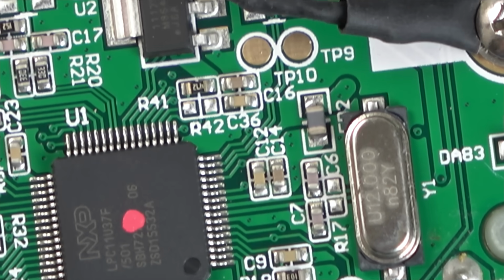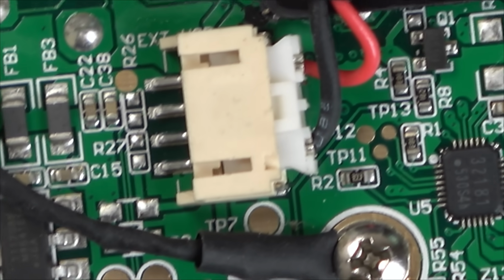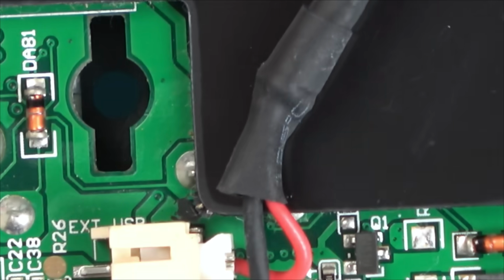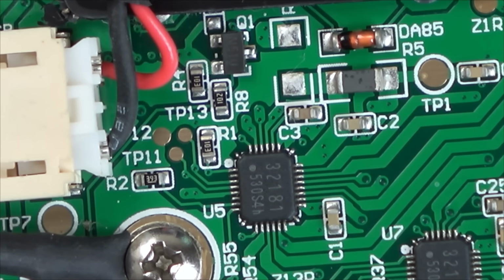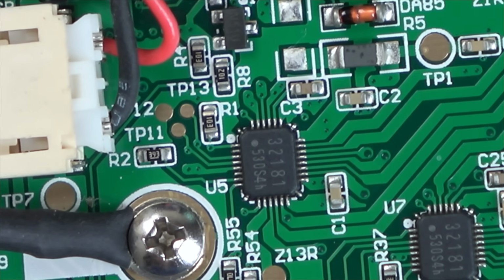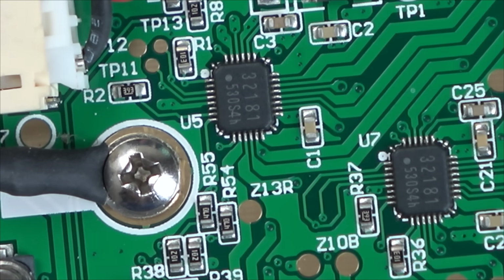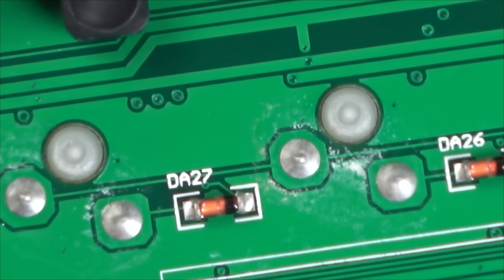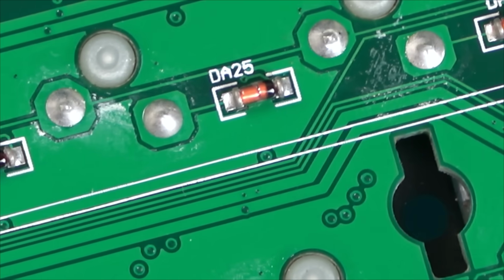So I think one of the traces is not getting to where it is, and maybe all the ones that are on the same colour are all part of the same trace. Because you know a keyboard's on a kind of matrix, isn't it? Like let's say if you had 50 keys, you're not going to have 50 different traces back from each key. Let's look back at the video and see what keys are coming up as different colours, and then let's see if we can trace those ones, you know?